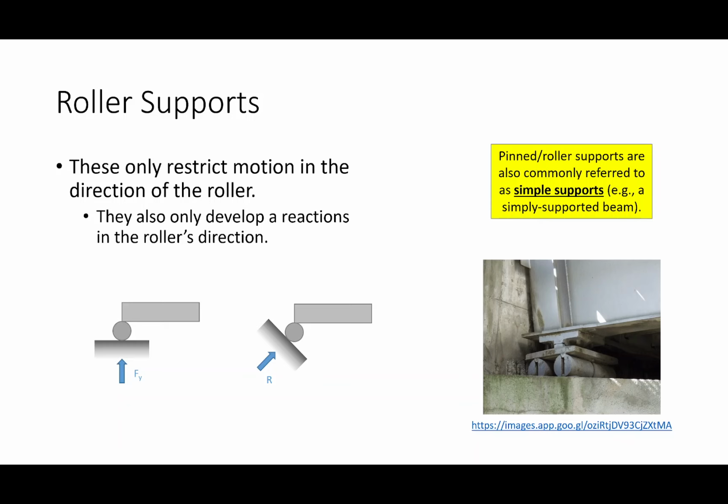All right, so a lot of times in bridges you'll use what's called a fixed bearing and an expansion bearing, and really the difference is how the beams or the flexural elements are attached to the foundation, okay? A fixed bearing is basically just going to have a plate with a circular hole in it, bolt it through, and it's not going anywhere. But an expansion bearing is going to have a slotted hole. So it's actually going to be allowed to move a little bit, okay?